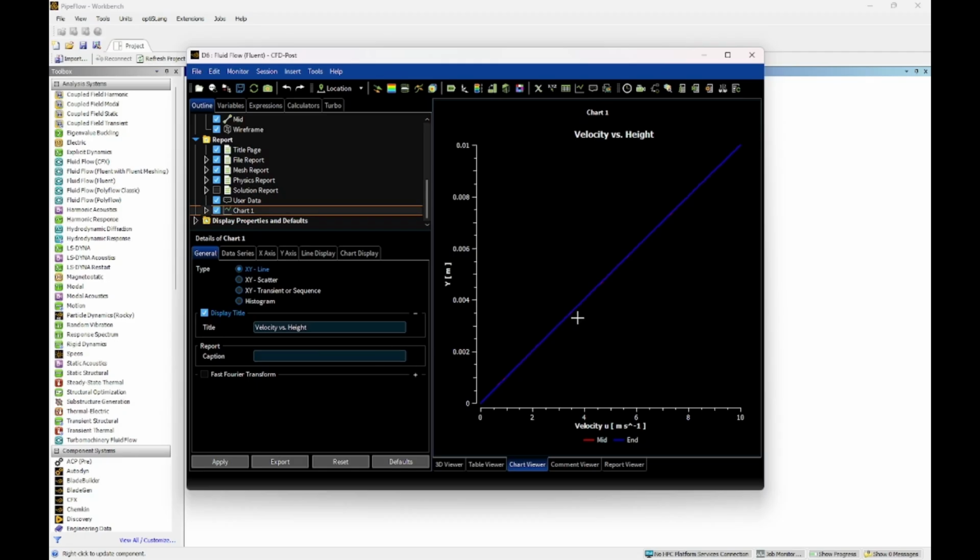Also, you want to make sure that these lines are 100 samples, because then you can get more accurate readings. If you do like 10, it'll give you at 0 it's 0, at like 20% it's whatever, and you don't get the in between. Especially for the Poiseuille and the combined, you might not get the true maximum. You just get an estimate. But that's it for Couette.